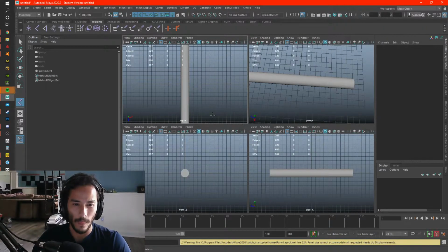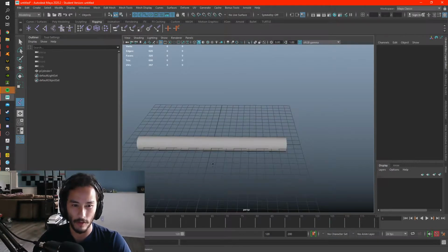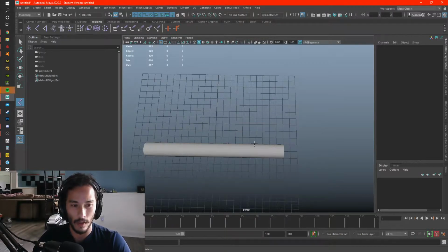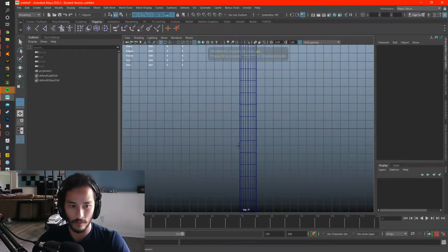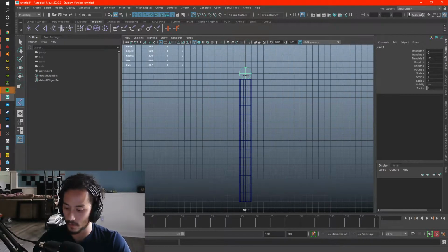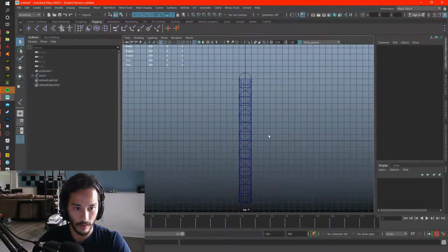And if anyone's using Maya, there's a weird thing with Maya. You have to make sure that you're clicking on the plane. Otherwise, it doesn't create a bone anywhere. But just to make life easier, I'm just going to make it on the top camera. I'm going to press and hold X so I can snap it on the grid. I'm not worrying, I'm just eyeballing spacing with the snap tool. And again, if you guys are using other programs, you can use little techniques like this.